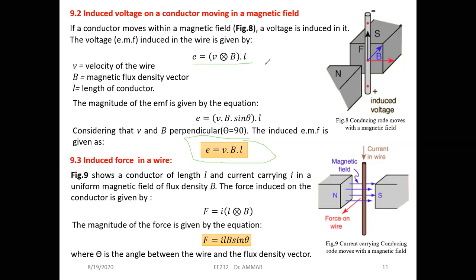To be specific, in AC generators and DC generators, because in the generator, we first excite the machine to generate flux, then we move the rotor with an external force in order to get a voltage. Those are the two cases of how we can get an induced voltage, according to time varying flux or according to a moving conductor.